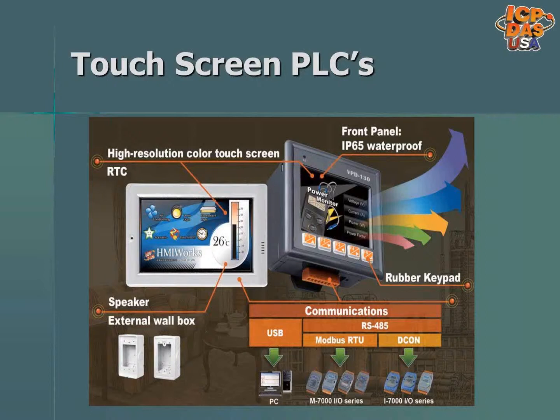TPD433 has both RS485 and Ethernet ports. TPD283 is powered over Ethernet. They can be used to show the status of equipment like tank and temperature levels, and to control equipment like opening and closing valves or turning on motors and lights.